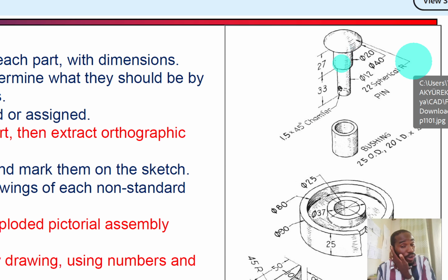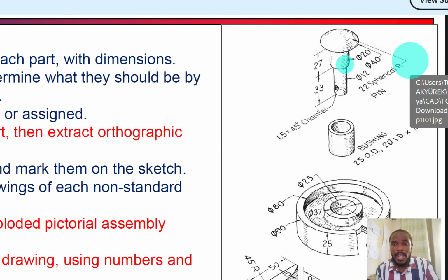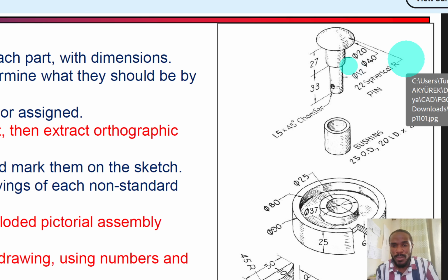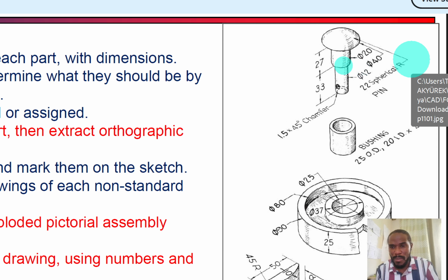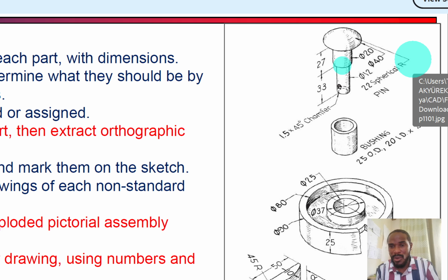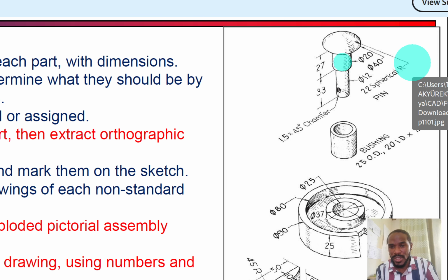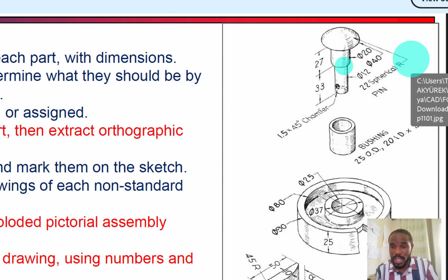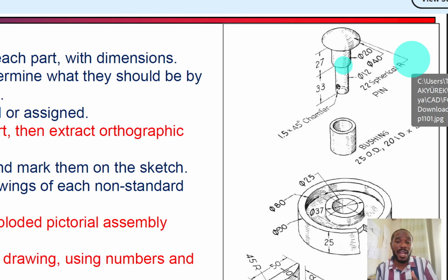So we will draw this first. Okay. Now, because of our time, I'm going to be doing things very, very quickly. So I'm going to select a plane where my cursor is, and there I will draw the circles both for this cylinder or shaft and this one as well, so that when I come to extrude, I can extrude in both directions in one go.